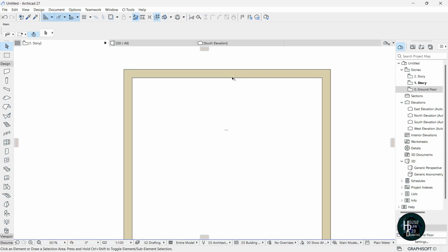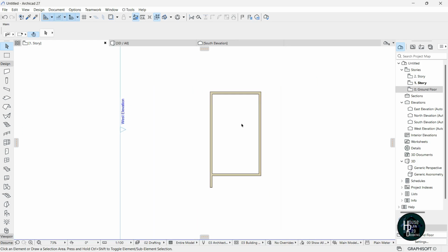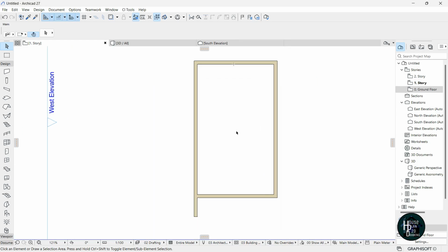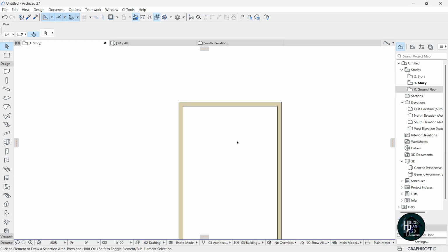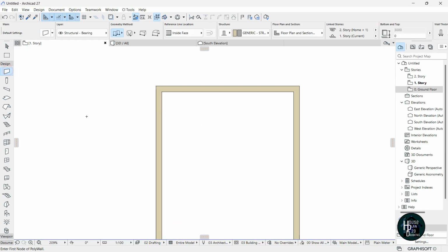All right, so let's continue the rest of the drawing. That's for the first story. That's very, very important. So let's click on the wall tool again. Click on the wall tool, put the cursor here, allow it to load up, and let's give a distance of 2824. Click enter, stretch it like this.